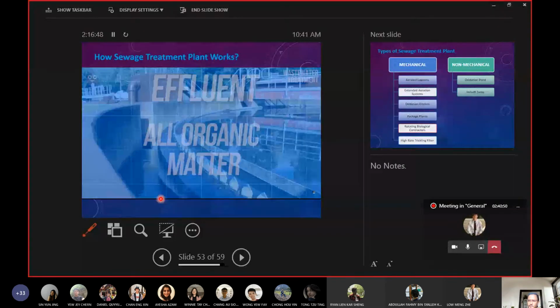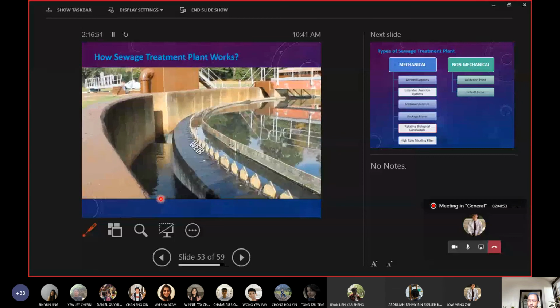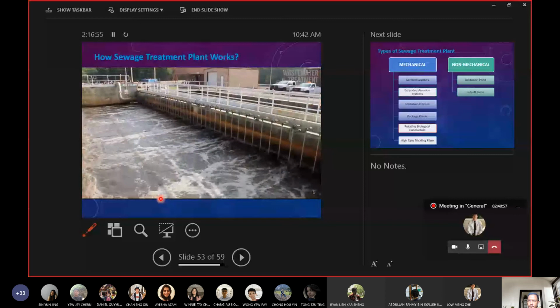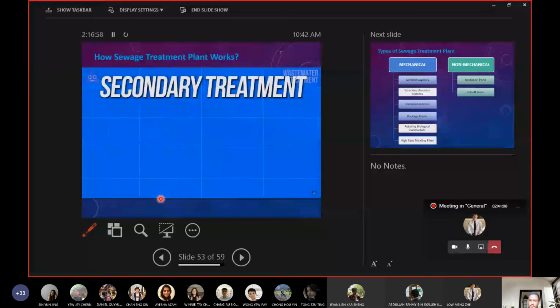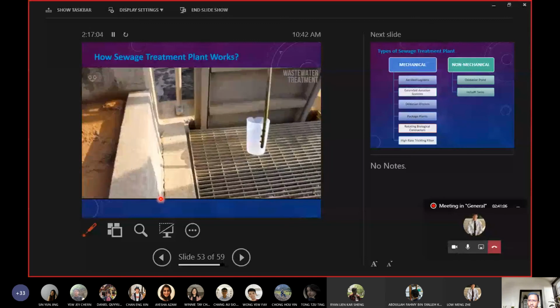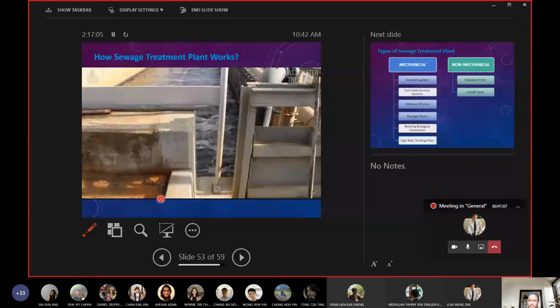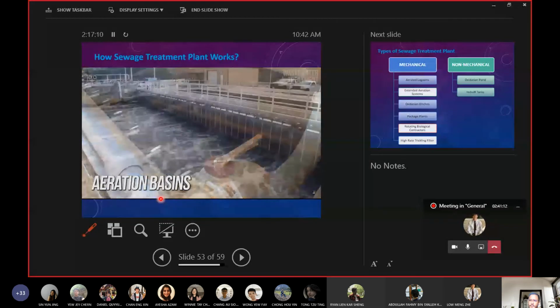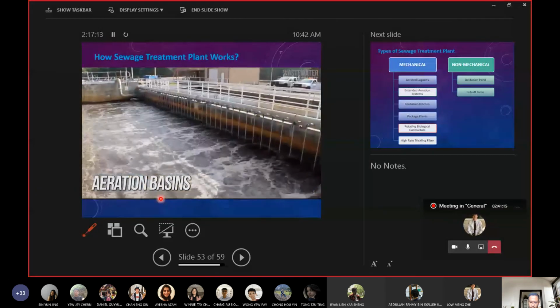The top layer of the clarified water flows over a weir wall and into the next basin process called the aeration basin. Now begins the process of secondary treatment, the sole focus of which is to significantly degrade the biological content of the sewage. In many cases, this process starts in aeration basins. Effluent flows into the aeration basins, at the bottom of which are hundreds, if not thousands, of tiny air blowers that create bubbles through the water.